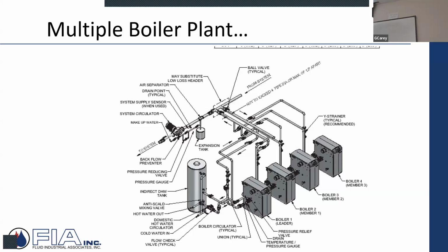But what's interesting is right there, those scenarios that I talked about, where only one boiler is running and the other 3 are off, and this guy here is pumping the building or the buildings, you're going to get some blending. You're going to get some mixing by design. And that's okay. And you get some kind of supply sensor feeding back to the BMS system that's controlling the fire in these boilers saying, hey, I need more, I need less, bring on a boiler, increase the firing rate, bring on two. All of that's happening all the time.